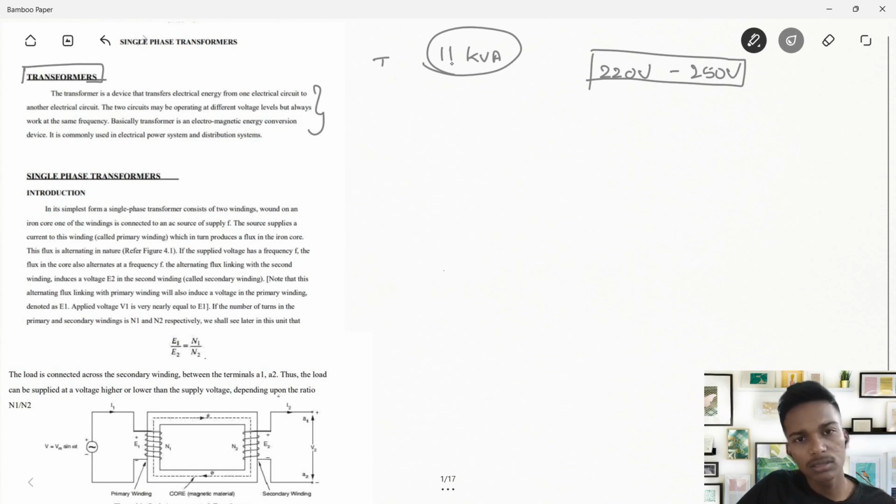In the line, if you transport heavy currents, it might cause a lot of electrical losses. So we transfer low currents with high voltage from one place to another. At a particular location, we want to send this high-voltage, low-current energy into households where we need low voltage and high current.